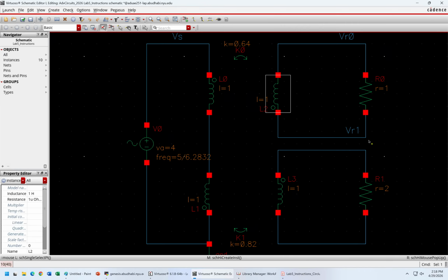If you force the ground anywhere, you are telling the system that this ground is physically connected with any ground that you define. To avoid that, we will always define the voltage drop across the component. To define the voltage drop across the component, I'll need this node voltage and this node voltage. So I'll not be defining a ground towards the secondary.